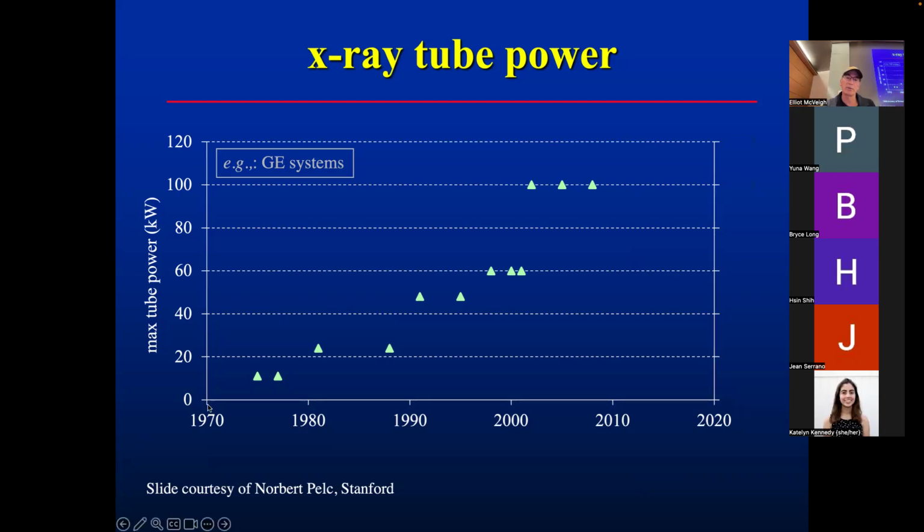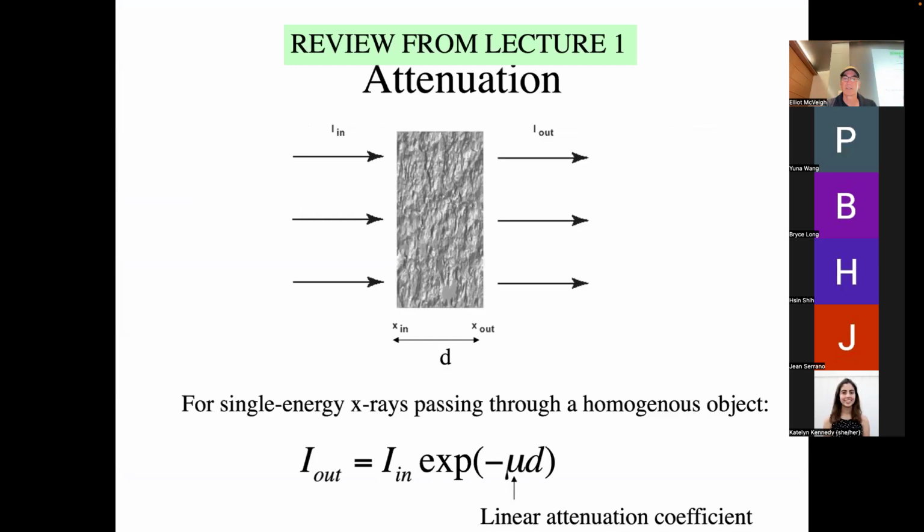And so that pushed X-ray tube technology up here. You've got a 100 kilowatt tube. This was in 2010. That's doubled since then. We're up around here now with these tubes that produce 1,300 milliamps at 80 kV. So this has been a huge engineering achievement as well. And there are multiple designs of X-ray tubes that achieve this.